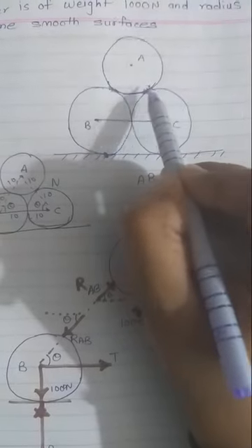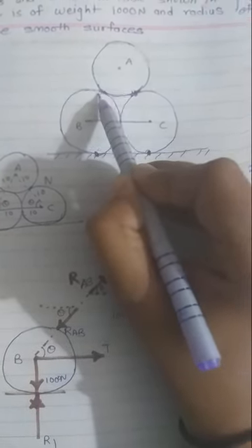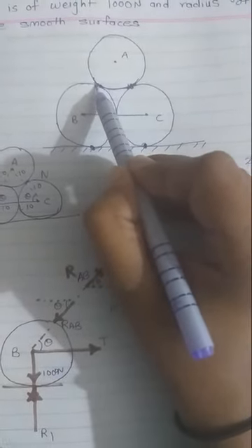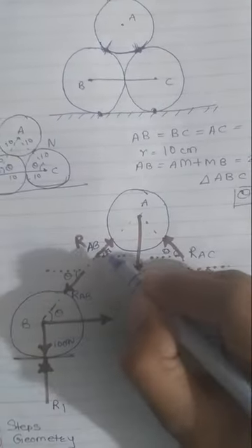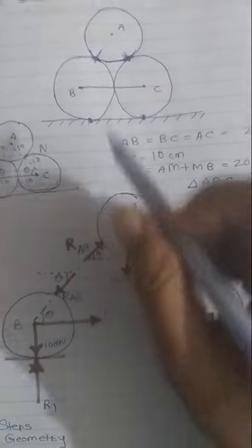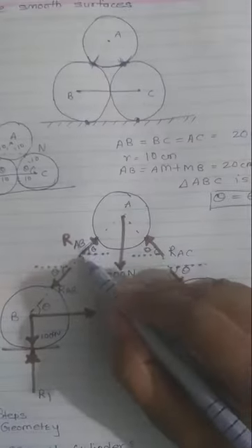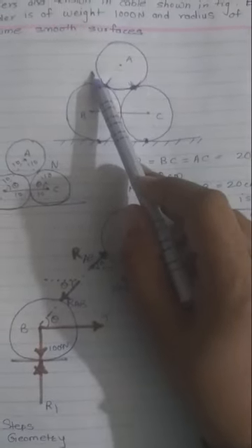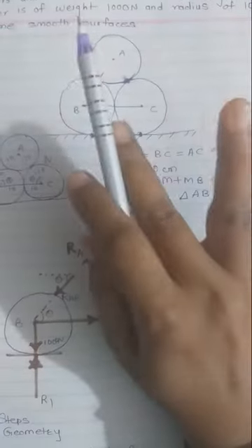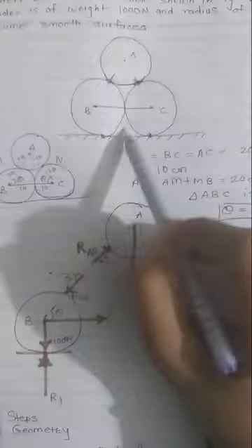Then these two contact surfaces, right? So there is a contact, that means there must be some reaction at these points, right? So I consider this as reaction AB for the spheres A and B, and reaction AC for the spheres A and C. Okay, so that is reaction AB and reaction AC for this sphere. Is there any other reaction for this sphere? This 1, 2 and 3, that's it. Okay, then go ahead for the sphere B.